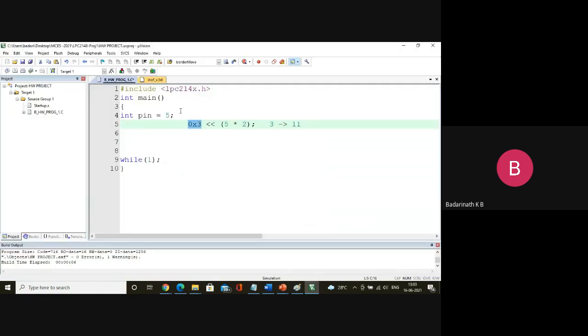Come back here. Now I want to make only those 2 bits 00. What operation do we use for that? We have learned in assembly language programming that the required bits of any register can be made 00 using the AND operation. Whenever we perform an AND operation, the required bits we want to make 0 have to be ANDed with 0, and all the remaining bits have to be 1. Now I'll invert the whole of this value by the invert operation.